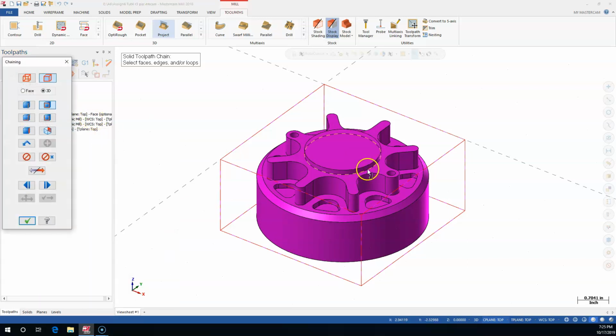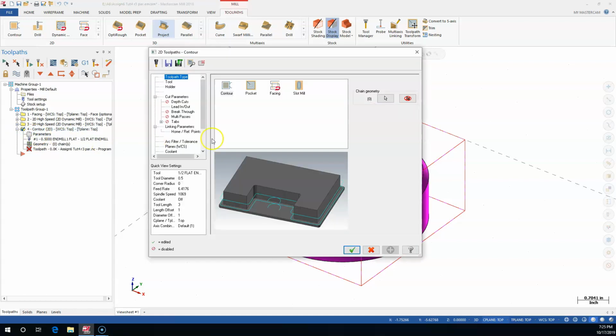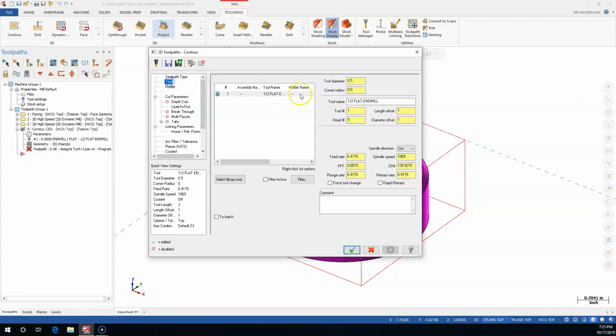And I'm leaving all of this with the 10 thousandths material so that I can do a finished pass at the, oops, I got ahead of myself there, talking. All right, so parameters, we're doing the contour, and the tool, let's stay at the 4000. I'm thinking 10 and 10 is working pretty good. This will be to depth. I'll just stay with my terminology, step 3.